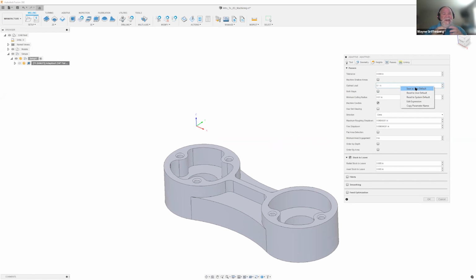So as you're setting up your toolpath and you're dialing in, of course, your feeds and speeds, but you're dialing in what the offset would look like, your step down and all that information, you can easily plug them in here. So I want this to go 3/4 of an inch. Actually, I want this to be 0.75. And so you can dial in and plug in your defaults and you could save them. So this way you don't have to reinvent the wheel every time you do a toolpath. We have the capability where you can plug in your standard defaults.